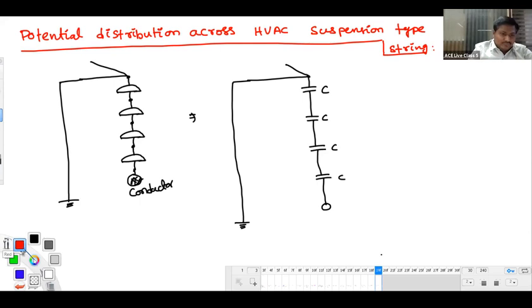Now I will show some points in this original string we have drawn. Is there any capacitance formation between those points or not? Please tell me. This is one point I have taken, and this is another point on the tower. Can we have any capacitance between these two? Yes or no? No, because both are at the same potential, so you don't get any capacitance.